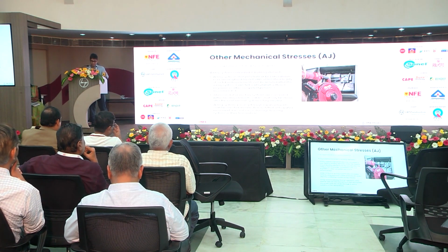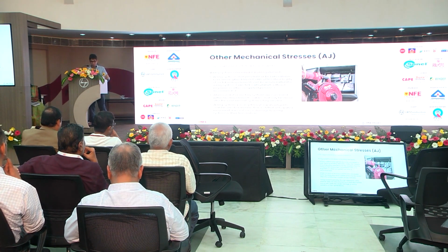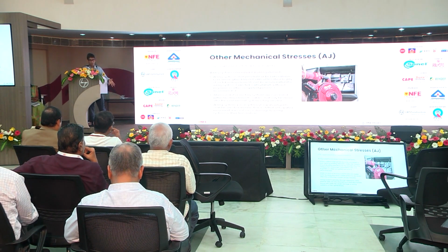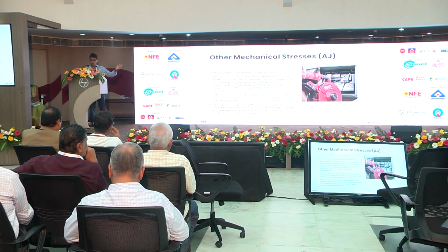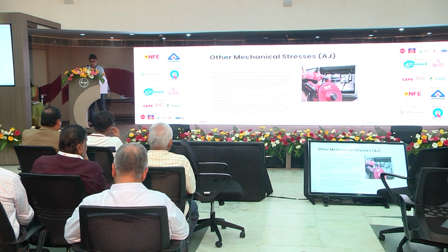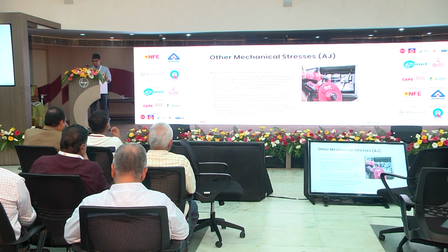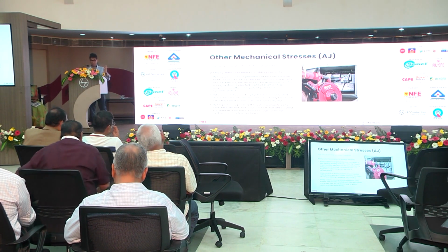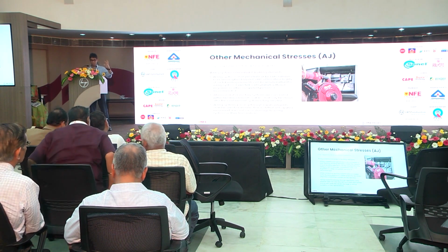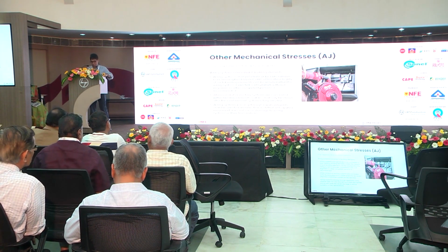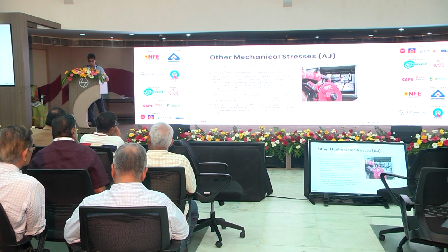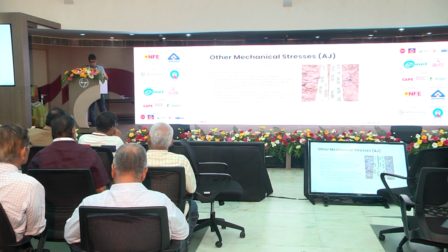So this wiring system, the conduit or ducting needs to be designed keeping in mind maintainability and serviceability, so that the installation is useful over its life. You can't break open the floor and the wall to perform maintenance or additions. So that's quite important. And expansion joints, again, you need to make sure that any stresses on the expansion joint, such as expansion or contraction, do not cause wiring damage to the system or even their terminations.